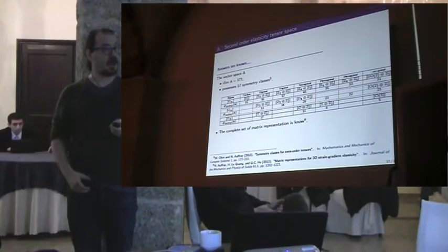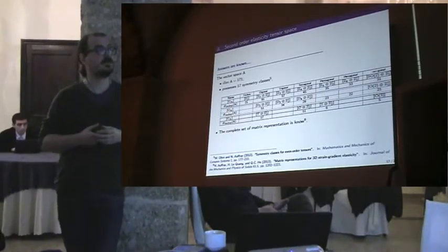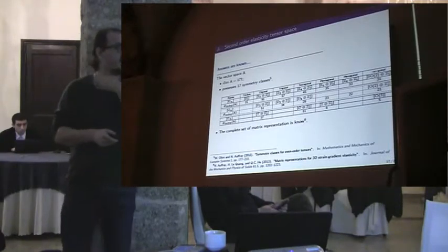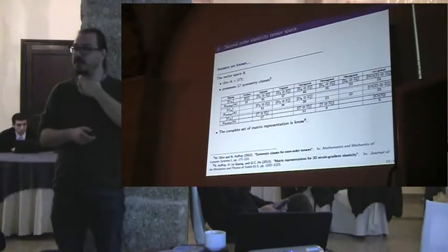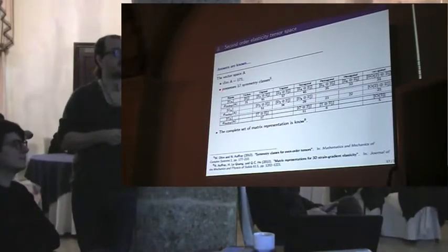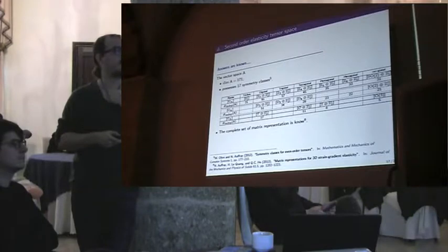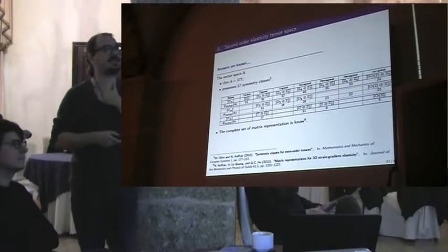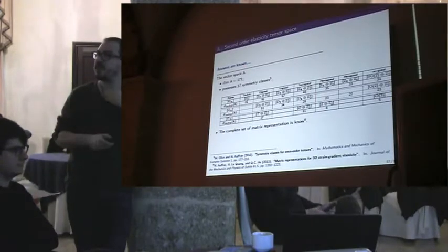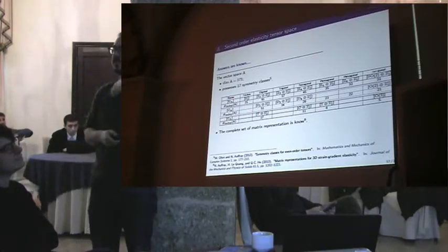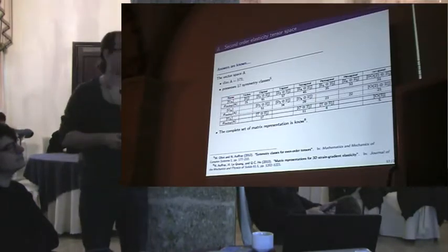For all the tensors in the constitutive law, results are far more recent. We obtained with Marc Olive, a former PhD student, the complete classification in 2013, showing that for the vector space of 6th order tensors endowed with the symmetries of strain-gradient elasticity, we have 17 different symmetry classes.